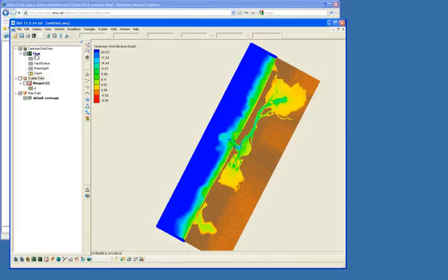What we can do is to click the flow in the data tree, you right click, and you can actually, let's duplicate this. So we're creating another exact grid of this flow grid. And so we have now a flow grid copy.